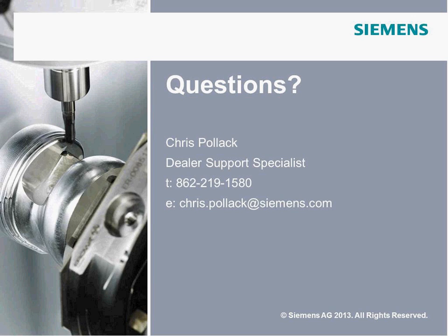There's a question: was it a different post-processor I used for this as opposed to the 840 control? I did mention earlier as well, but let's briefly talk about that. It isn't. It was the same post-processor. Certainly, some of the critical things that we were talking about was really just those slight machine differences. Be careful, but the core code was the same between the 808 and 840. Certainly, the difference is the ShopMill type protocol that you get in the higher controls.